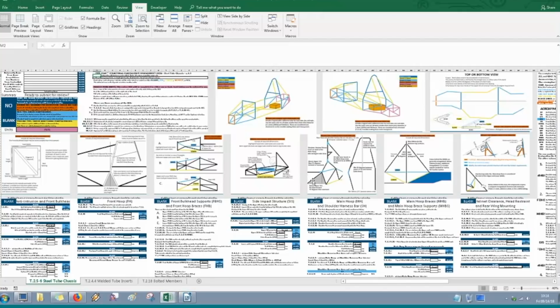If any regulated part of the frame is not steel tube, use the non-ferrous/hybrid/monocoque SES. For EV cars, the HV enclosure file is due at the same time, and the IAD is due later. A note, if the accumulator is composite construction, that's contained entirely within the HV enclosure SES. So an EV car with a steel tube chassis, you use the regular steel tube SES, and the composite accumulator goes into the HV enclosure SES.